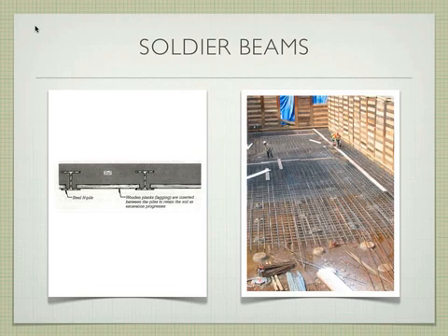This is the existing soil that you're trying to retain. The normal place that the lagging or plank is going to go is right inside here. That's typically where they're going to put it. Sometimes they'll put it back here, but it has to go either on this surface or on this surface. They prefer this surface because it's locked in between these two webs, so it can't slide. That make sense? Up here it can slide off and then cave in. Make sense to everybody? Those are the beams.